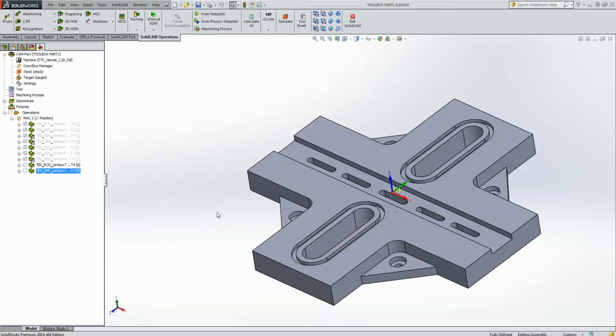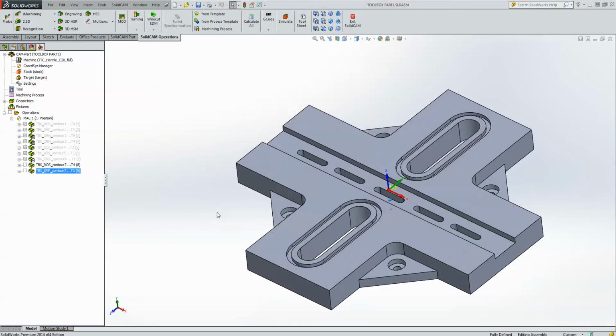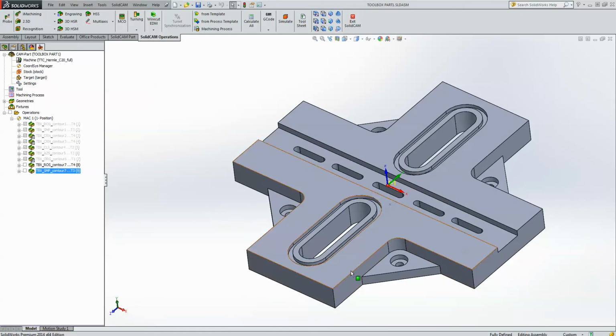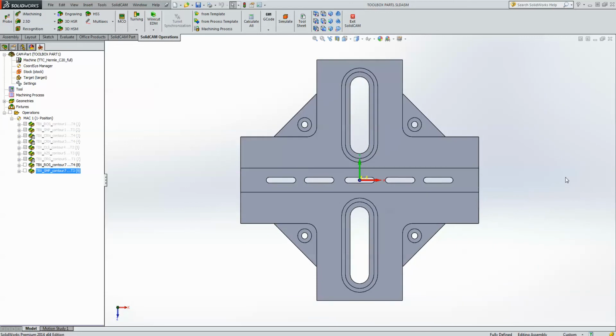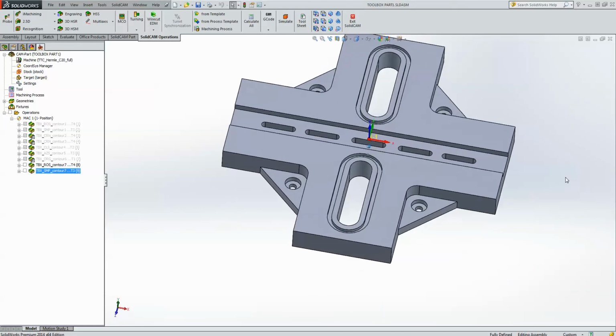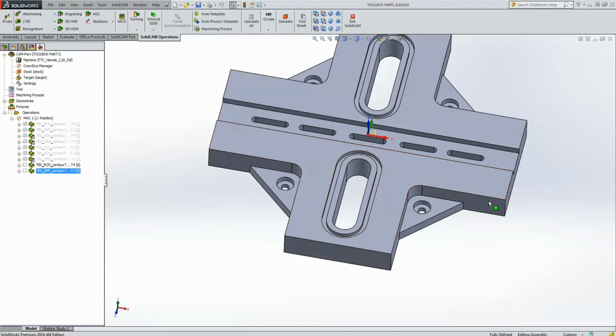Okay, now the next thing I like to do is I like to work on these corners over here. I like to machine out the material over here, around here, up until the step, as well as this corner down here. Now, if I were to do this without ToolBox, there are two ways I can do this. The first way was to do a profile operation over here, but by doing a profile operation, I would have to use the option of clear offset.